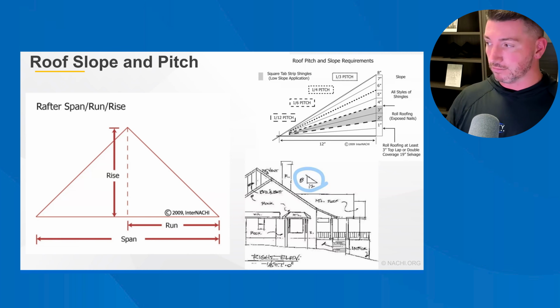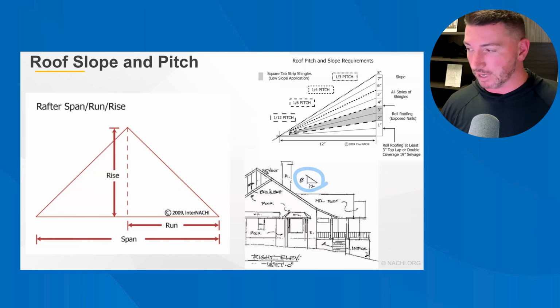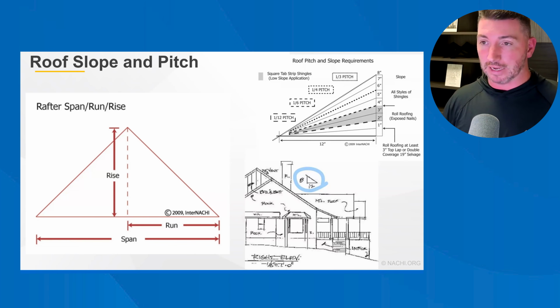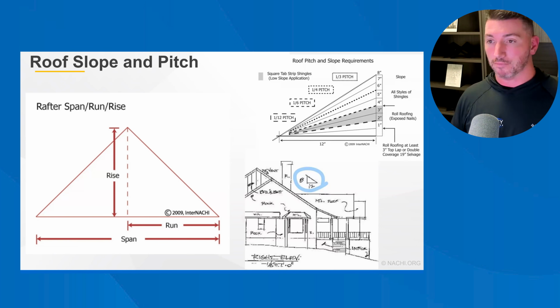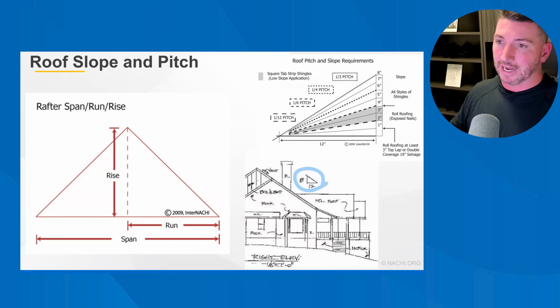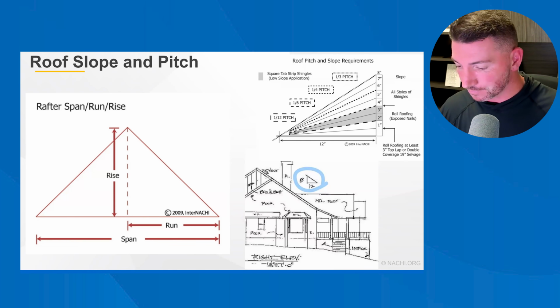So in that comparison, a 1/12 slope is a very flat roof or very close to flat. A 12/12 slope is a very steep roof. It's a 45-degree angle. In the insurance world, they've got different categories of paying out for roofing crews to do different slopes. Usually between 2 and 7 is one category, 7 to 9 is another, 9 to 12 is a whole other category, and then there are steep charges for anything above 12.